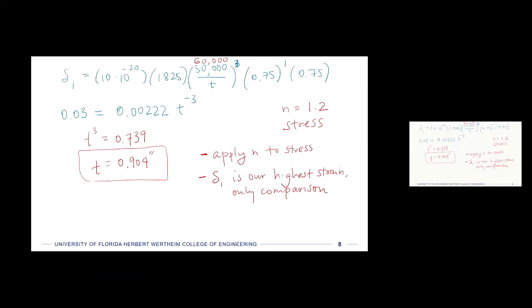And that all of the other assumptions that went into this equation are also holding. Okay, so if we do that, we get this thickness of 0.9 inches. That is a very thick wall on a 10-inch pressure vessel, right? If the diameter is 10 inches, that means 2 inches of that is eaten up with the walls. And this really can't be considered a thin-walled pressure vessel.